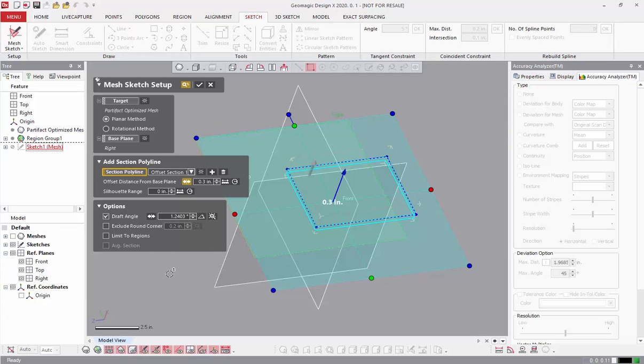And just like everything else in Design X, if we want to use the original design intent of this part rather than just some extracted value from the scan, I do have override capability here, and I can type in 1.25, enter, and it will use that. I almost called it a whole amount or whole value, but it's a fractional value. At any rate, now